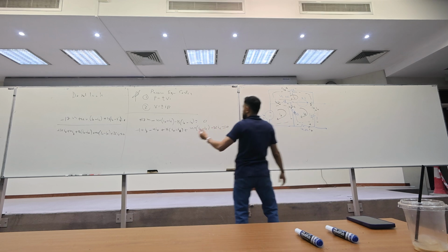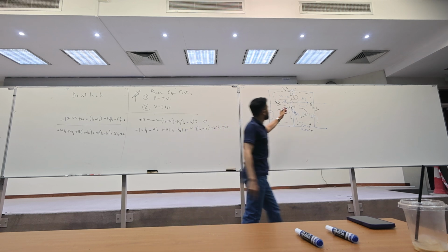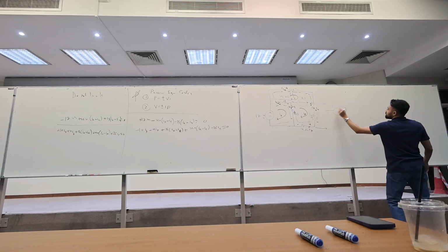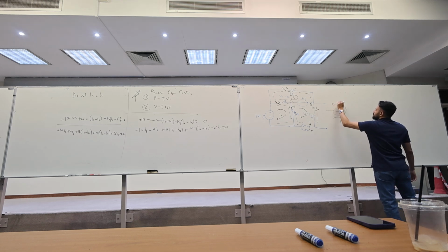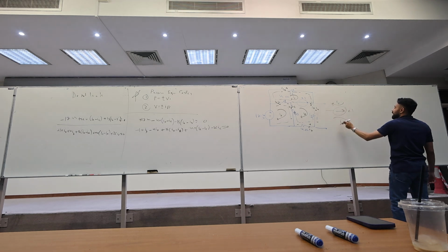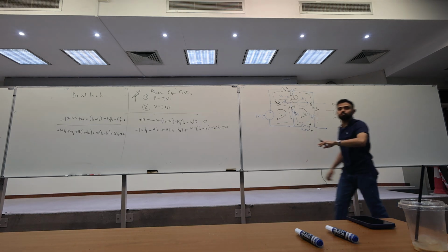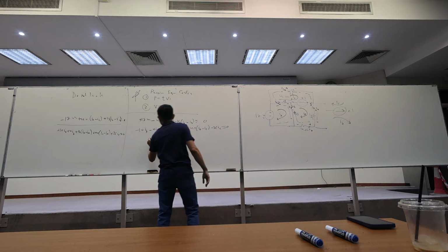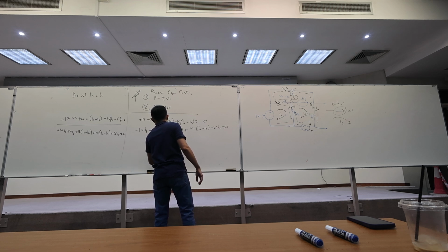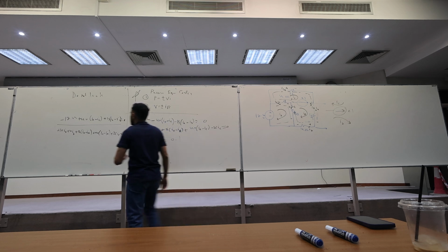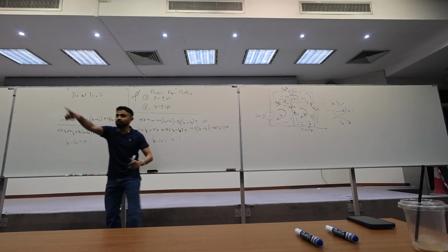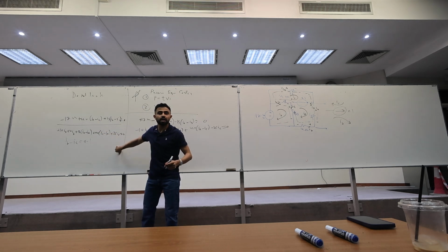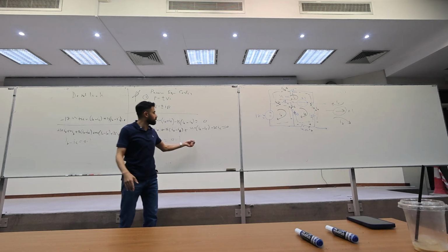And then the last equation, what is it? The mesh. So we have a current source that has IB going here, IC going there. So that's a 0.1. So IB minus IC equals 0.1. Both methods are the same. From here, can you solve it? 3 equations, 3 unknowns. I'm not going to solve it by hand. I'm going to solve using our system solver.